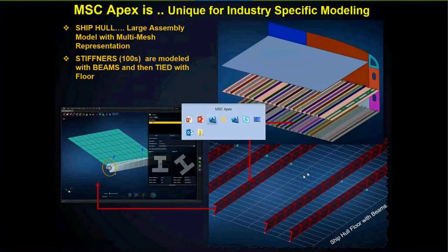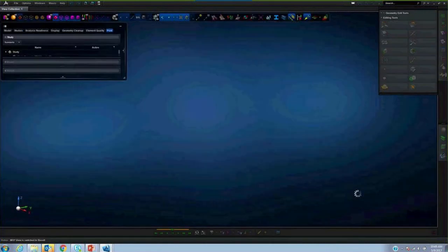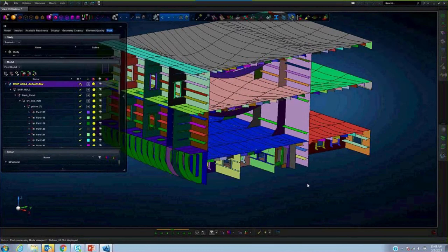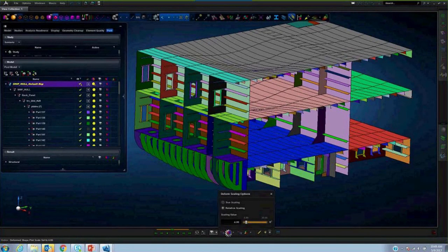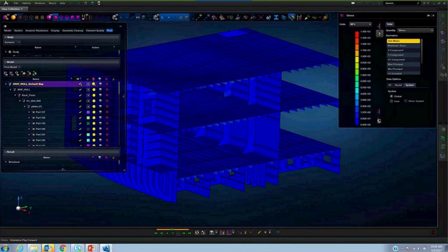Let's take a look at if it has run through. All right, simulation is done, right? Now let's go ahead and explore the results. Okay, all right. Now let me make the scale of displacement maybe 4 millimeter, and the stresses, and animate. Okay, now if you see here, probably the high stress is about 1.5 e power 3. Let me just set it to 400